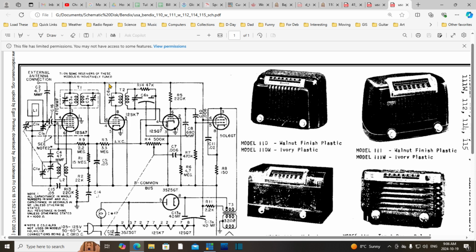Well, I'm not surprised this radio has a howl in it. Most of these radios have a separate screen supply line, if you like, and there's a big fat capacitor on the supply line. You can't put a big fat capacitor on this line because it's also working the plates. The screen here has no capacitor to ground. Well, I think that makes it really susceptible to exactly the problem we've got. That's what I think.